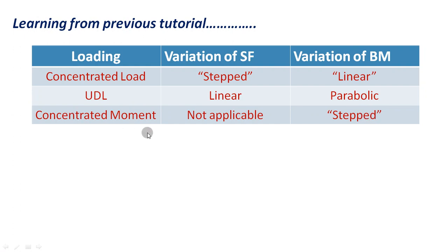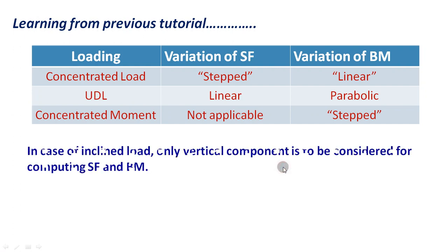As far as concentrated moments are concerned, the variation of shear force is not applicable because direct moments have no role to play in the development of shear force, while the variation of bending moment is just like the variation of shear force in the case of concentrated loads. That means it is a stepped function. So concentrated loads are to shear force what concentrated moments are to bending moment, as far as the nature of variation is concerned. A very important point to remember is, in case of inclined load, only the vertical component is to be considered for computing shear force and bending moment.